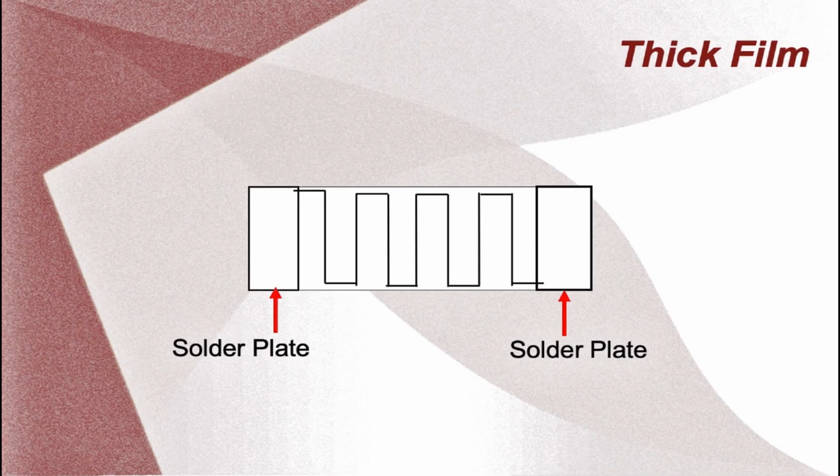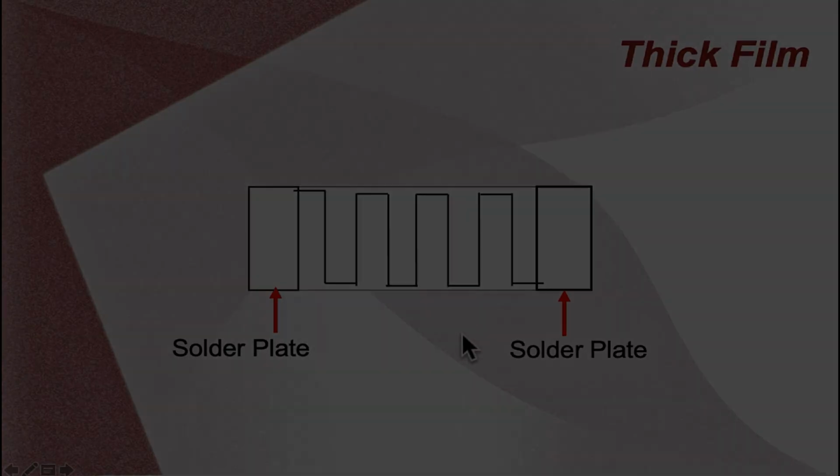After they trim it with a laser to reach the right resistance, they apply a coating for protection, install the solder plate, and it is ready for the customer. The Vishay manufacturer is completed. Now we're going to go to the second manufacturer.